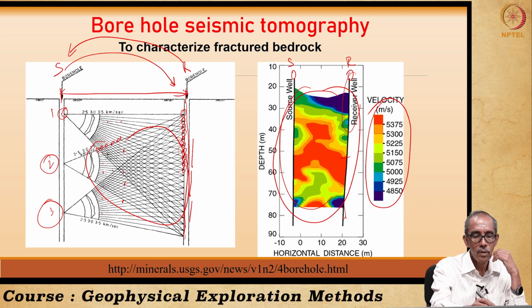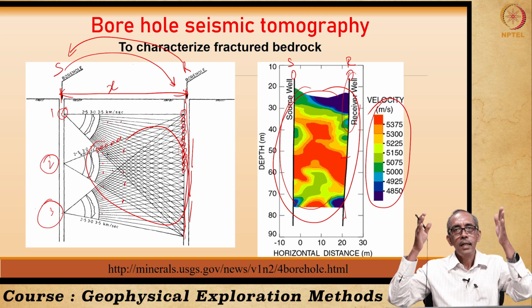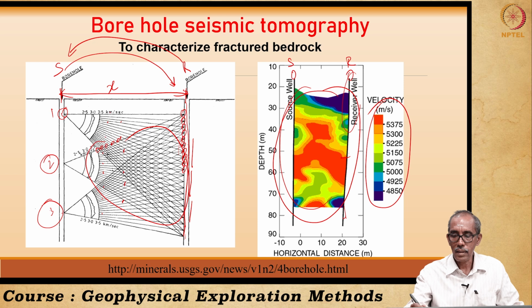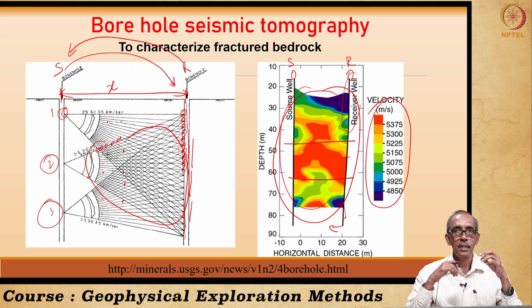This is the distance between the 2 locations. However, this distance may vary at different locations of the borehole. As this borehole is a little bit inclined, the distance x is high here. When you are somewhere here, the distance between the boreholes is a little less. So, we need to use the correct distance to estimate the shear wave velocity. So, this is how seismic methods are used to understand the weakness or weak